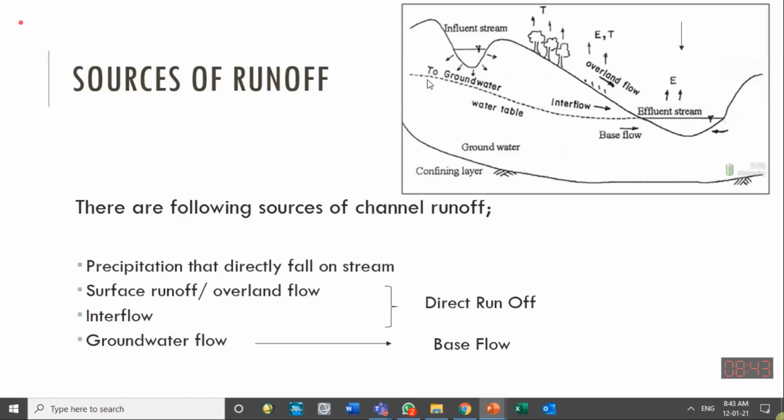But after the monsoon, after the rainy season, the groundwater table rises. Groundwater is not constant or static. It goes up after the rainy season and goes down in the dry season. So groundwater moves up and down depending upon how much recharge there was from precipitation in the previous months. If the groundwater is as shown over here, it will not provide any water to the stream, so this component will be 0. But in the case of this stream, groundwater is providing some component.